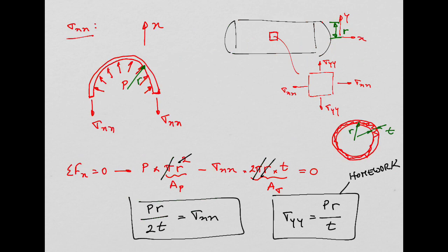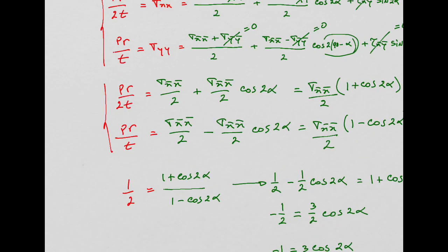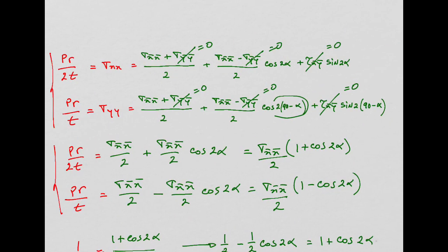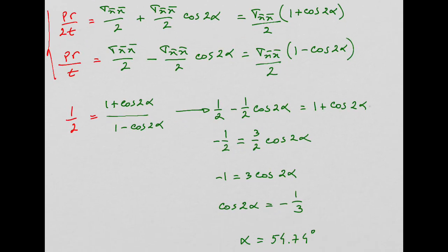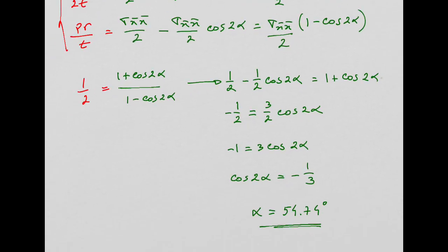But I think this example is very nice because it explains that we get the loading in the global coordinate system, with its stress transformation here to get the stresses from global to local or vice versa. And then we impose our optimal conditions on the stresses in the local coordinate system to obtain this optimal angle, right?